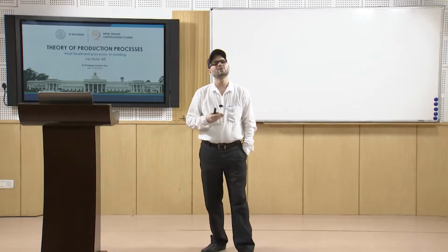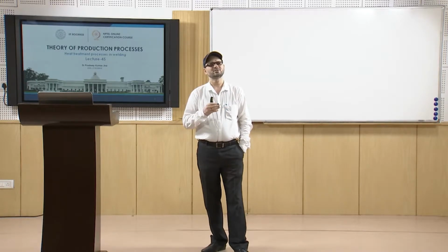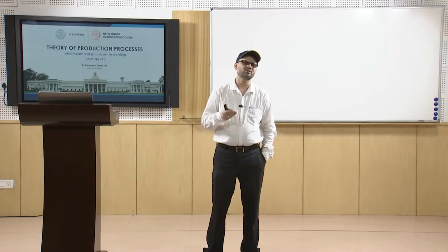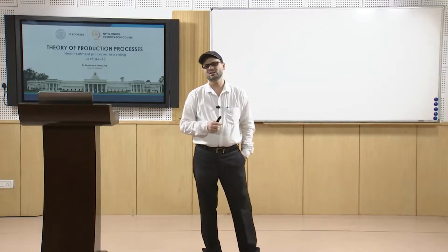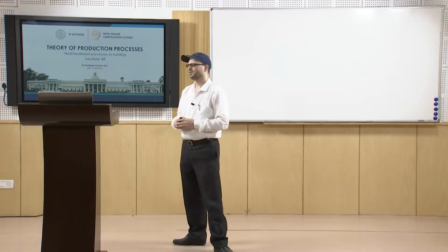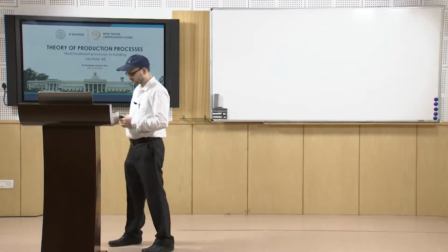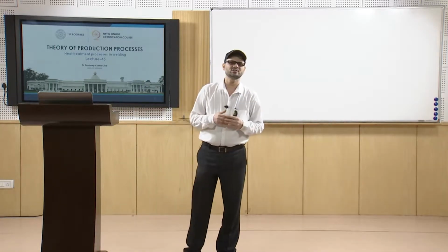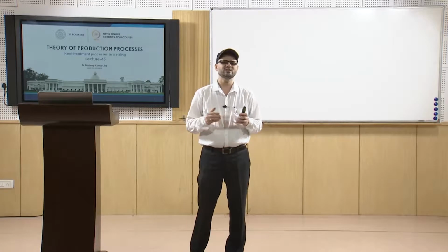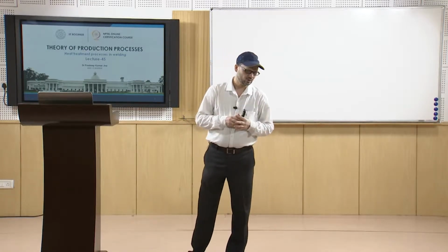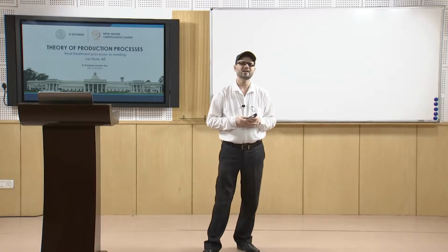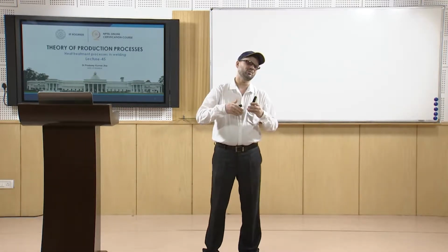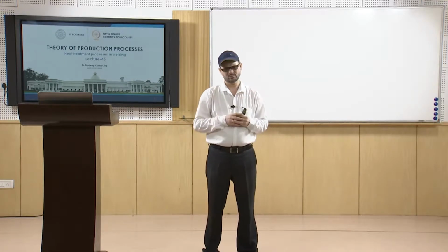or the temperature effects in welding. Now, that should not be in such a way that it affects the mechanical properties. So, for that the heat treatment processes are employed in the weldments so that you get the desired structure, desired mechanical properties. Especially what we see is that because of the uneven heating and cooling cycle, residual stresses are developed.